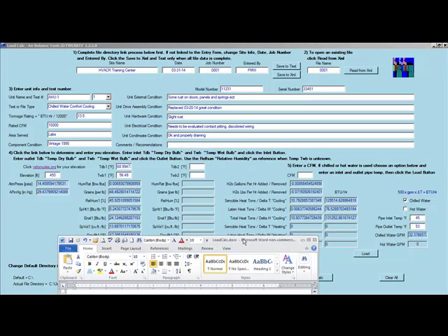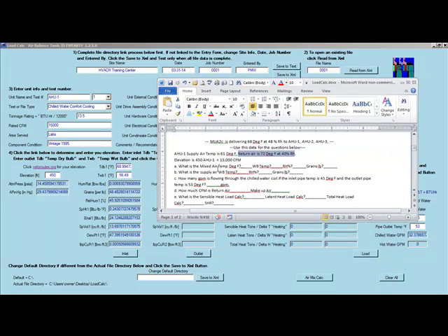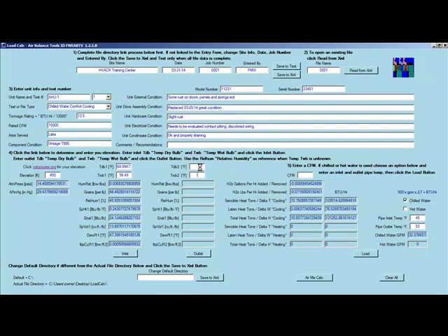So now we want to go back and say our supply air temperature is 61 degrees. At this point there is no transfer in grain, so our grain is going to stay the same. So we're going to go ahead and say 61, 61, and that's why I kept that value. So we want to match our grains, and we got 48.48, 48.47. To me that's close enough.